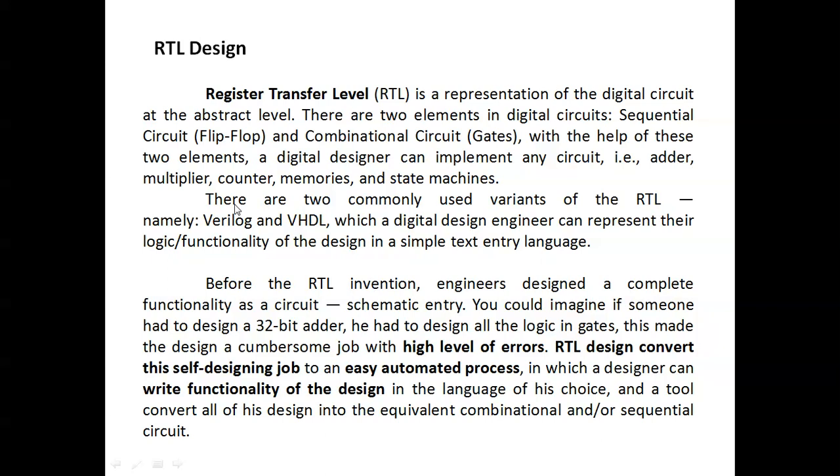Okay, now the RTL design. RTL is register transfer level. It represents a digital circuit at the abstract level. There are two elements in a digital circuit. One is the sequential circuits, such as flip-flops and counters, and the other is the combinational circuits, such as gates. Examples are AND gate, OR gate, MUX, encoder, and decoder.